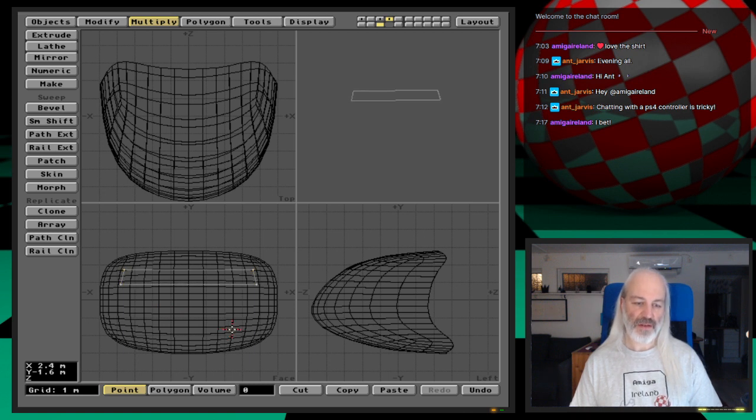Okay. One note here, pressing undo. If I selected them like this, Lightwave records that, and it will create that. As we've said earlier, Lightwave keeps a record of which element we have selected first and in which order. So we should be aware of that. That's why we should select our elements in order. So if we want to do something like that. Okay.